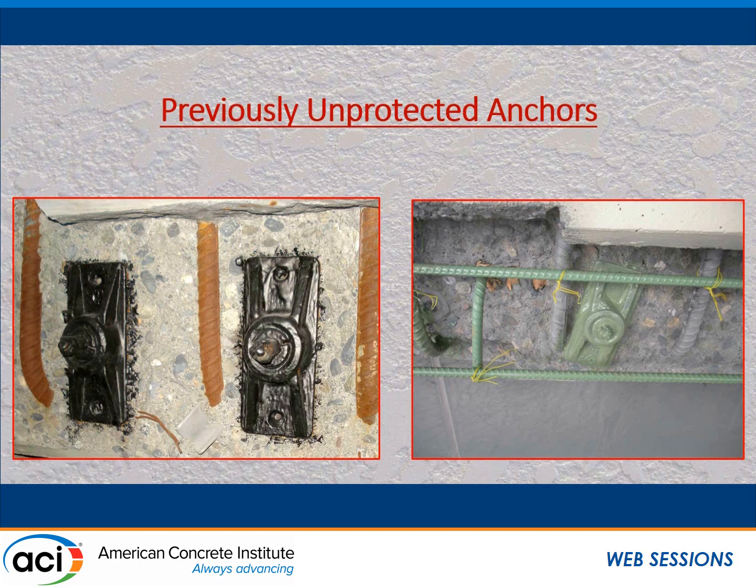There was a building built in Seattle, and they did not mandate encapsulation. They suggested that some kind of protective coating be put on the anchorage. So there's a variety of coatings that can be put on, and if you are looking at structures probably before 2000, you're going to probably find conditions where there is no encapsulation, no protection of the anchorage. And that may or may not be bad, because it really depends on the environment. It depends on the quality of the concrete that is encasing the anchorage. But in these particular cases, we opened this up, prepped everything, and applied a multiple coat protection system.